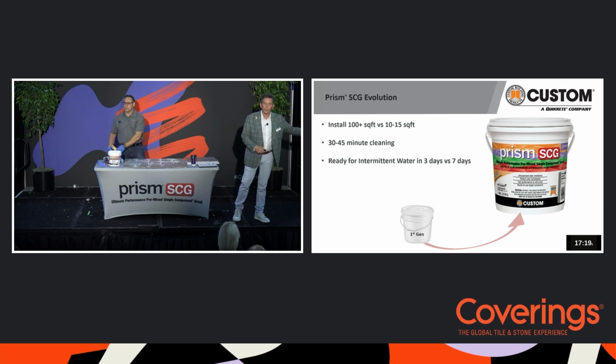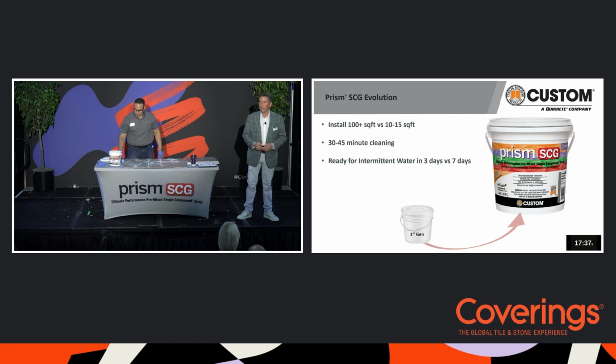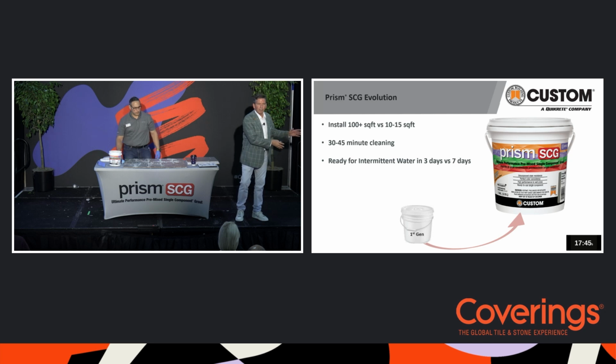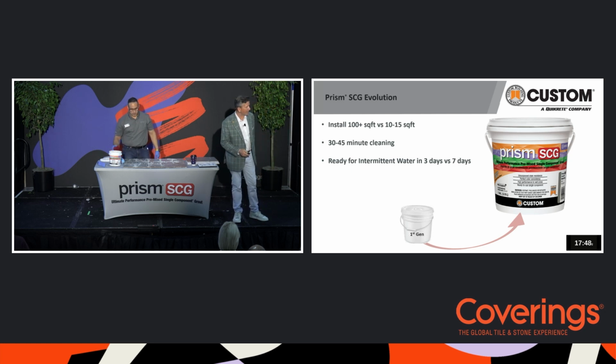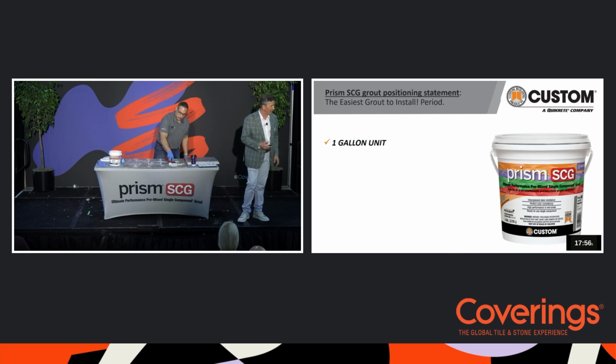And now we're able to reduce that wait time for intermittent water exposure, specifically shower applications, which in the first gen category, that's using technology that's 14 years old. Does anybody have a cell phone that's 10 or 14 years old? Now we can move and open those showers up in 3 days instead of 7. 7 days is prohibitive in a builder scenario. Now it's not. 3 days works perfectly in that timeline. We can open up to light traffic in 24, and we can open it up to full service also in 3 days for commercial applications.